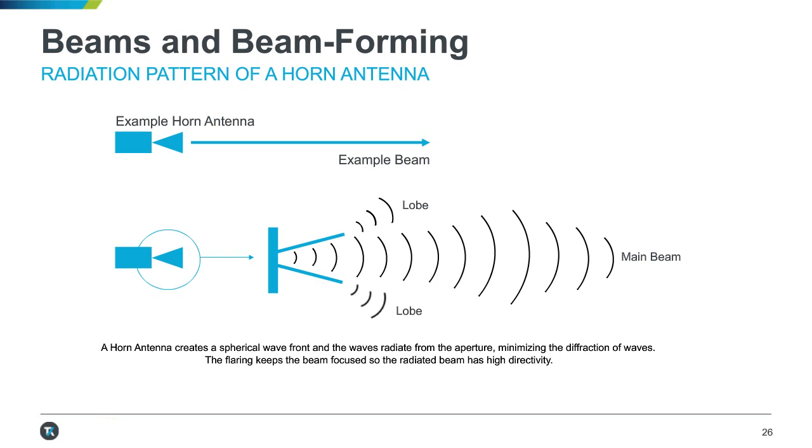And what we want to make sure when you're designing the antenna system is that the lobes are as low as you possibly can make them within the cost constraints of the design. The higher the lobes are, the more incidences of clutter you're going to get. So that's one thing to consider. But also, when you're in a high clutter environment, you probably want to have a good representation of your antenna pattern to be able to verify that you're identifying real signals versus false signals.